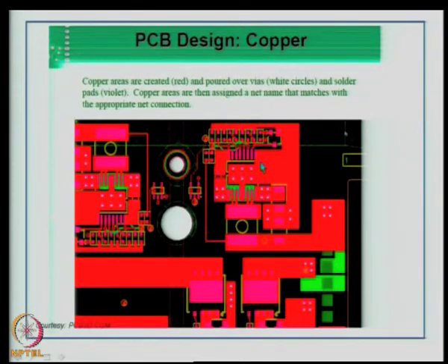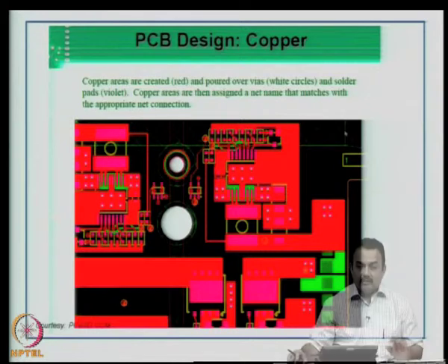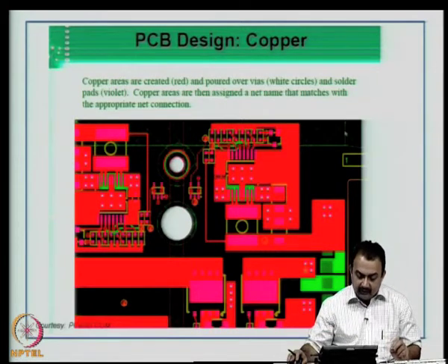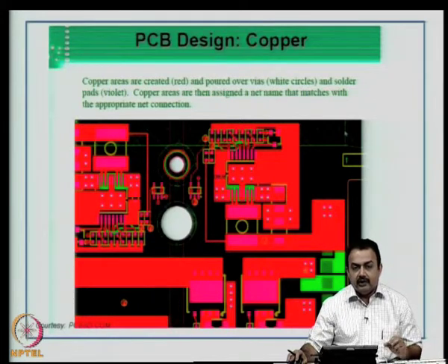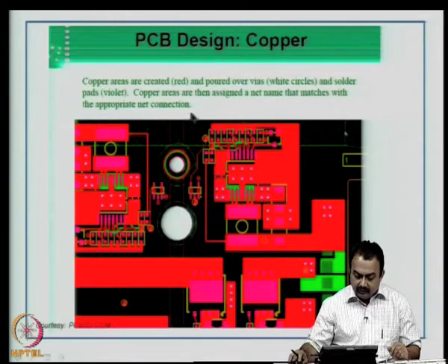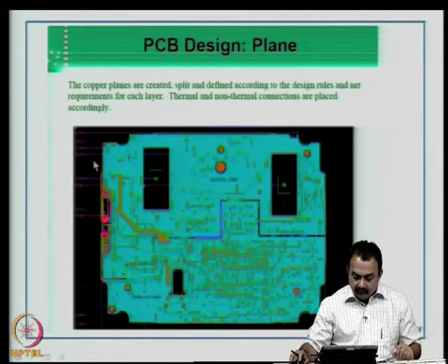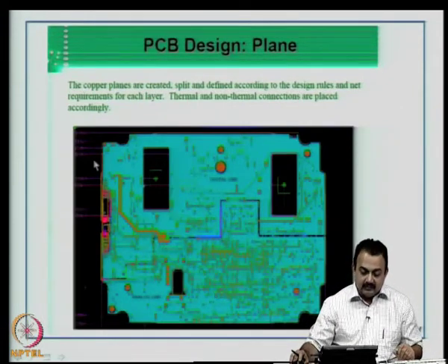So, this is a very important period in your electrical design, where you assign the area or the copper pour area that you decide for your electrical circuit performance, and sometimes the traces end with the copper. Okay. So, this will act as ground areas, and these are very essential in a multilayer board. This is the plane of a PCB design.